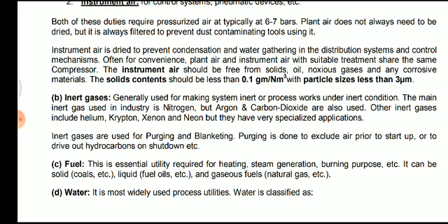The instrument air should be free from solids, oil, noxious gases, and any corrosive material. Solid content should be less than 0.1 gram per normal meter cube with particle size less than 3 micrometer.